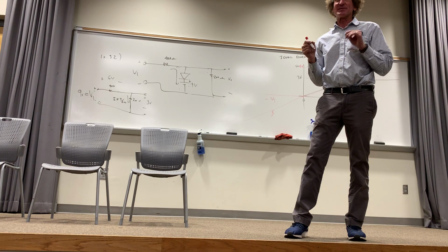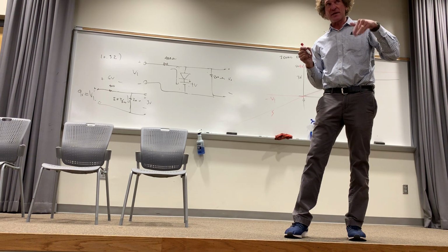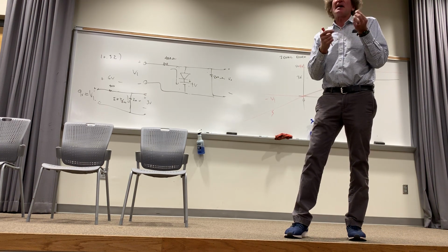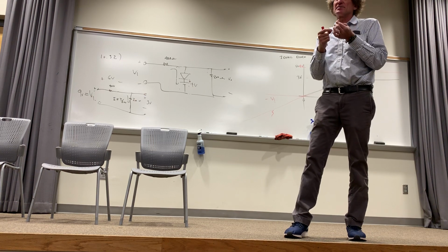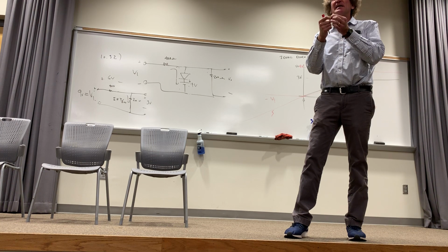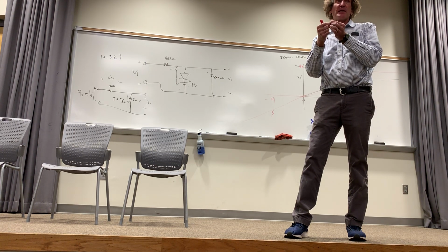what actually happens is this. You're starting to look at a possibility of breakdown of the diode. It's current in the wrong direction. So the way I get around that, if the diode has a reverse breakdown strength of say 4,000 volts, and I needed a breakdown strength of say 12,000, then I put 3 in series, and they have to be identical, or this doesn't work. And then I would get the breakdown strength.